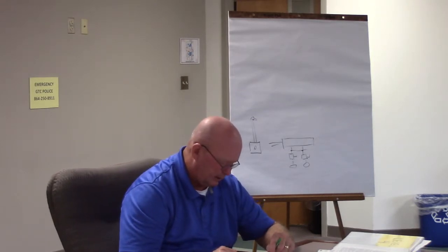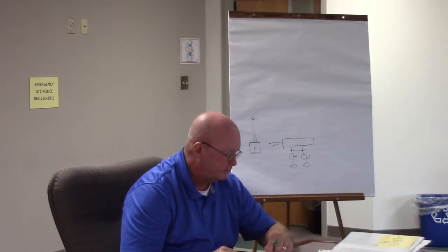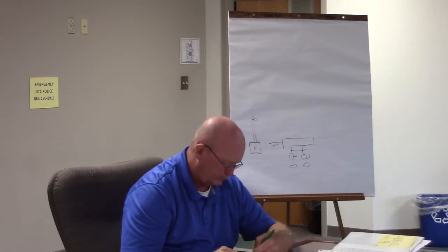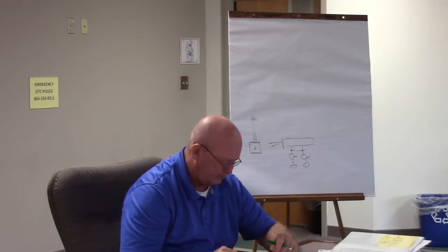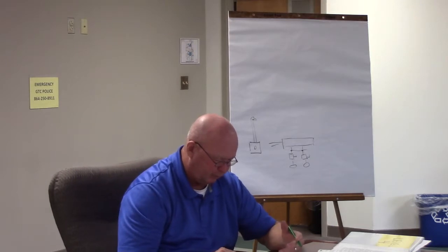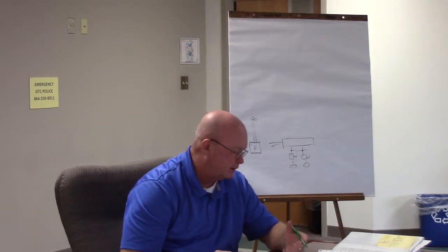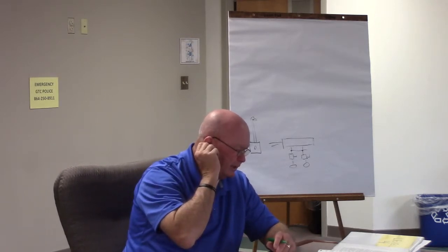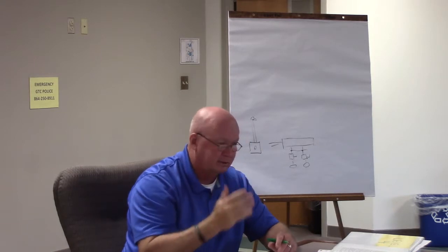Okay. Number 19. NEC section 240.21(C)(6) will permit secondary transformer conductors in lengths up to 25 feet when certain conditions are met. So we go to NEC, we won't go there now. 240.21(C)(6) permits secondary transformer conductors in length up to 25 foot when certain conditions are met. And the conditions are actually listed there. On page 10, there's actually 3 bullet points that list those conditions.